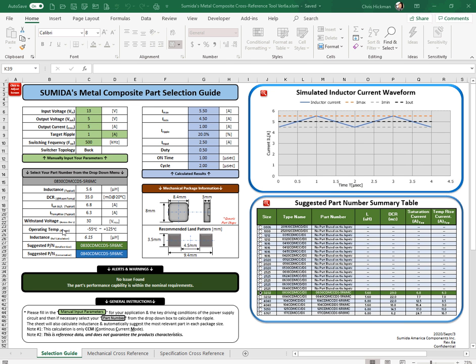The final three rows in this area are for the inductance value reference calculation we previously discussed, followed by two suggested inductor solutions, the first being the smallest part available that meets the conditions generated by the user's input conditions. To ease use of the sheet, this is the part number that is already preloaded in the drop-down box in the gray area. But there's also a secondary suggestion which is a bit more conservative. This is the next largest size that meets the requirements.